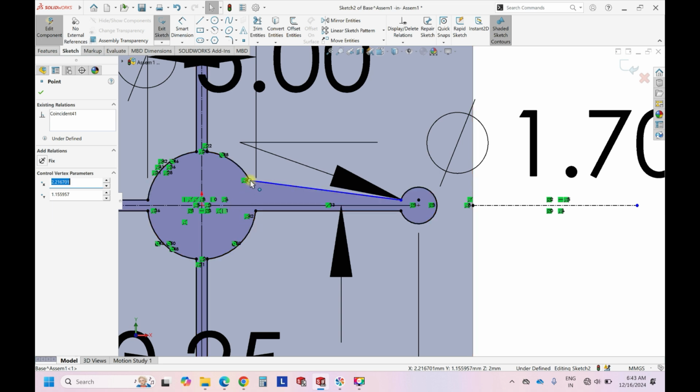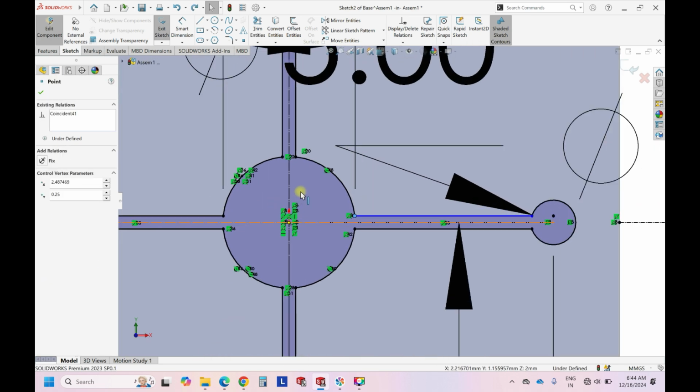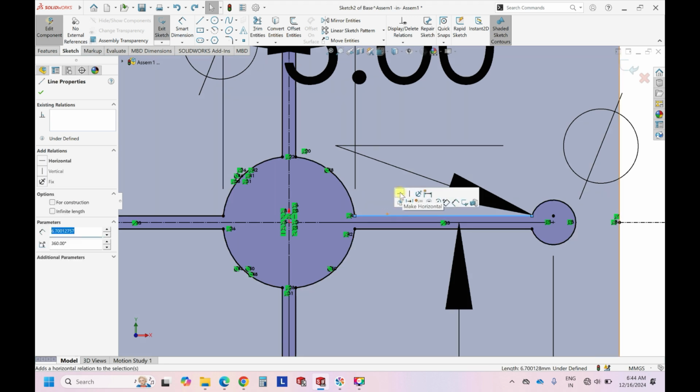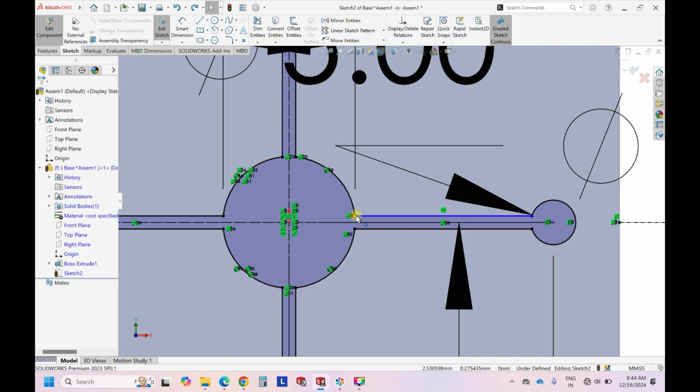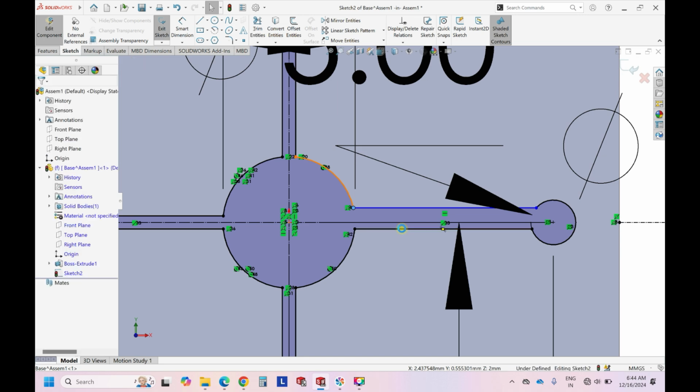So this is a major deviation that I did so that we can visualize it, but minor deviations can happen always. So just press Ctrl Z, and now try to see that this line is not horizontal, that is the reason it is moving. So let's make it horizontal. Once you did horizontal, now it is horizontally moving, right? So it means that it is not constrained in this axis.